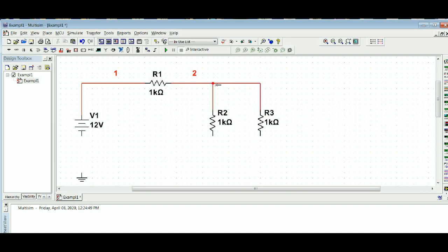And do notice you have a dot here. So if I were to wire something, and don't do this, I'm just kind of showing you, and I want to cross a line, and I'll make something really weird here for a minute. There's no connection at this point because there's no dot. So you have to specifically, by releasing and re-clicking the mouse button, set a point. This is simply a crossover on a line, or the wire if you will. It means nothing, so I'll select it and delete it with the keyboard.